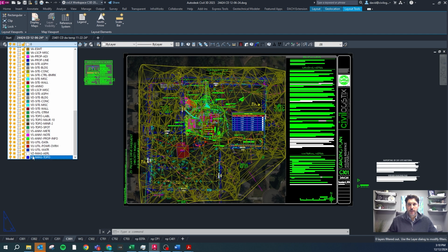VZ is specialty. That's on the survey layer, so all of our images we put in there. So you have your 2-letter designation, and then you have some more additional descriptive characteristics. Also want to draw attention to some of them have AN1 for annotation, and then some just have improvements, site improvements, like the building, the asphalt, curb and gutter, things like that.